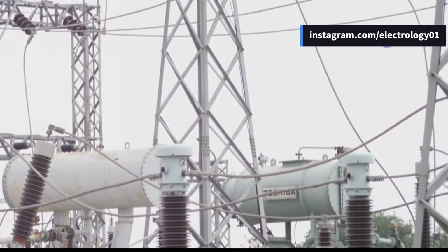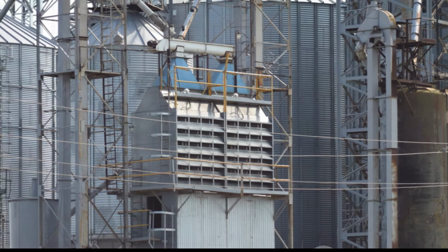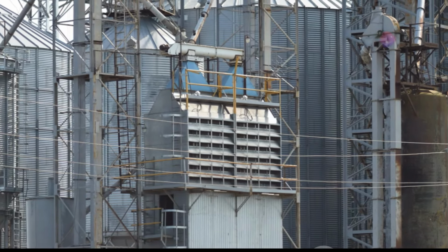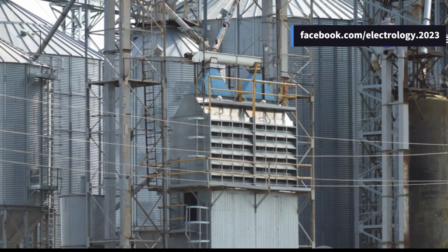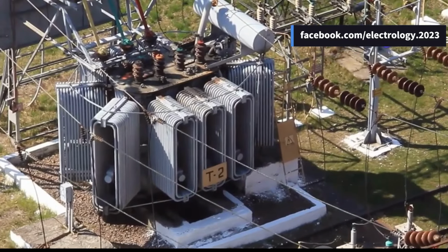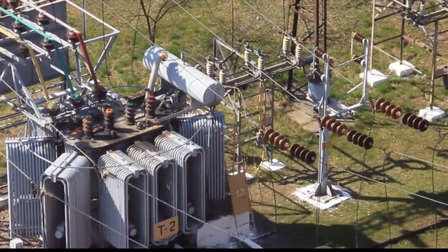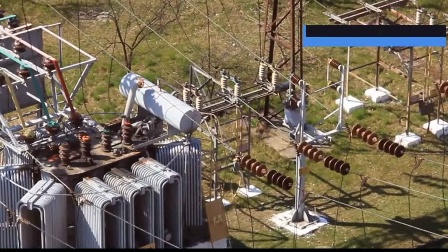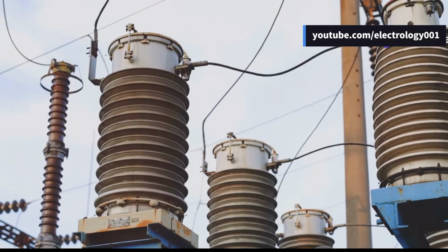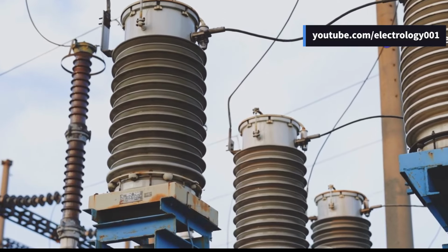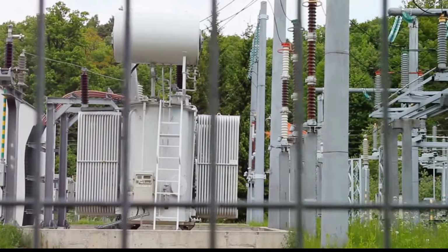However, autotransformers are not without their disadvantages. One of the major concerns is the risk of a higher voltage impression on the secondary side if the insulation between the primary and secondary windings fails. Also, they can produce severe short-circuit currents under fault conditions, which can lead to more serious damage. The changing primary and secondary phase angle can introduce complications, especially in systems where phase relationship is crucial.